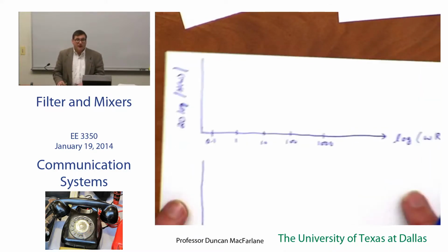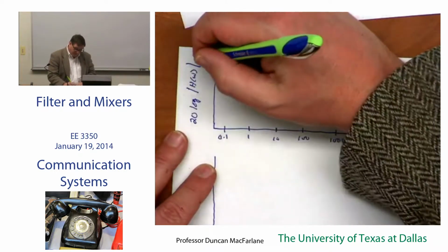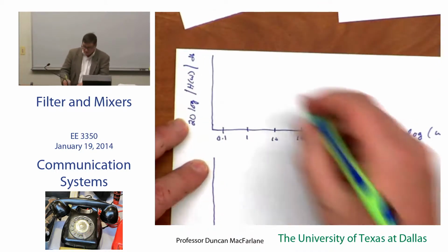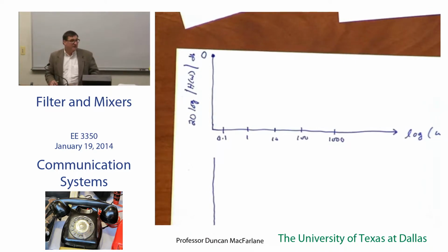And because I'm worrying about the voltage, it's 20 log of the voltage. And so the units here are dB. And the maximum in this passive system is going to be 0 dB. No change in the signal. I like dBs in the vertical axis because they add instead of multiplying together, and adding is easier to do than multiplication in your head.